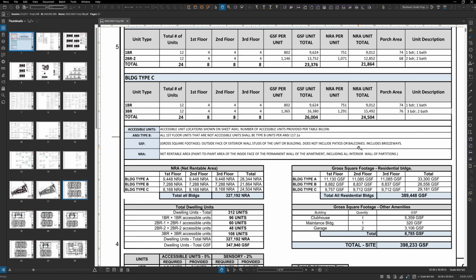The International Code Council makes your International Building Code, your National Plumbing Code, Fire Code, all those books, they all kind of go together. There's also, folks see ADA a lot, you know, the 2010 ADA, and the 2010 ADA does have section 809 for accessible units. Those usually, that section and then the 5% versus the 2% come into play when you have a Title II funded job, HUD job, Kentucky Housing Corporation job. But we always try to do 5% for accessible units across the board.